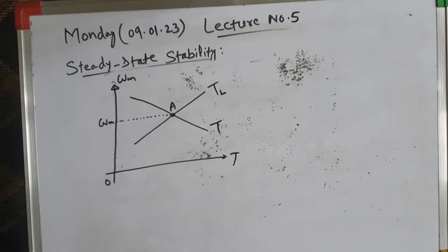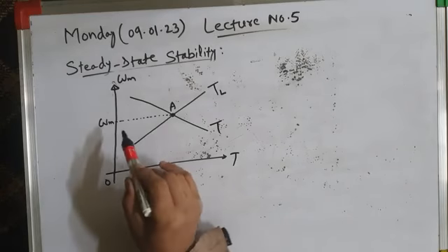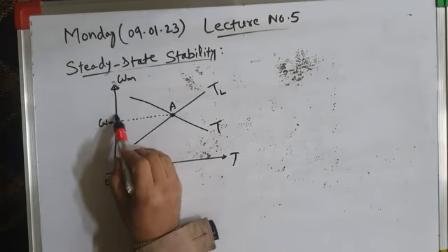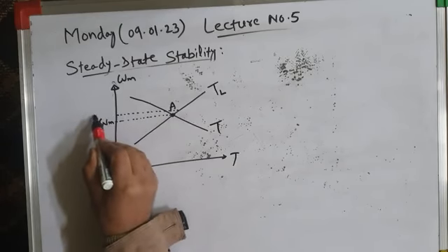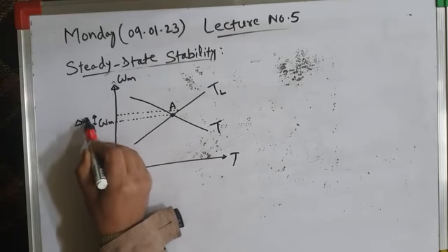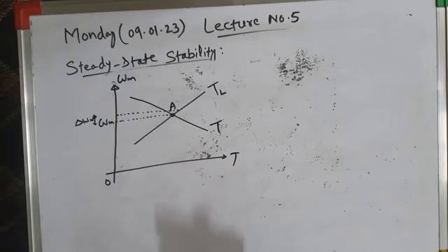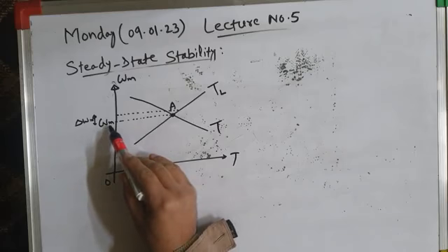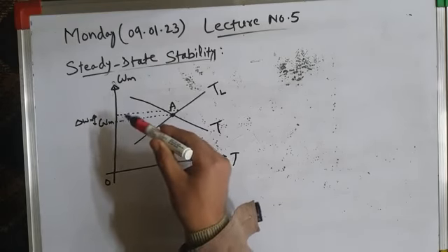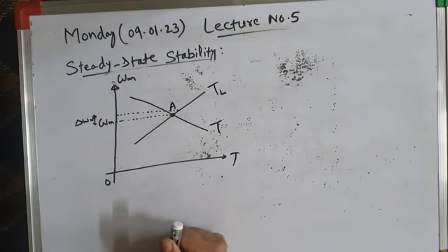Now we have to verify whether this operating point is a stable operating point or an unstable operating point. For that purpose, we will give a small perturbation to the load torque or the speed. Let us suppose the speed of the motor or drive increases by a small increment, delta omega m. Due to some reason, the drive is not running at the rated speed. The speed may temporarily increase due to some disturbance or perturbation in the system.